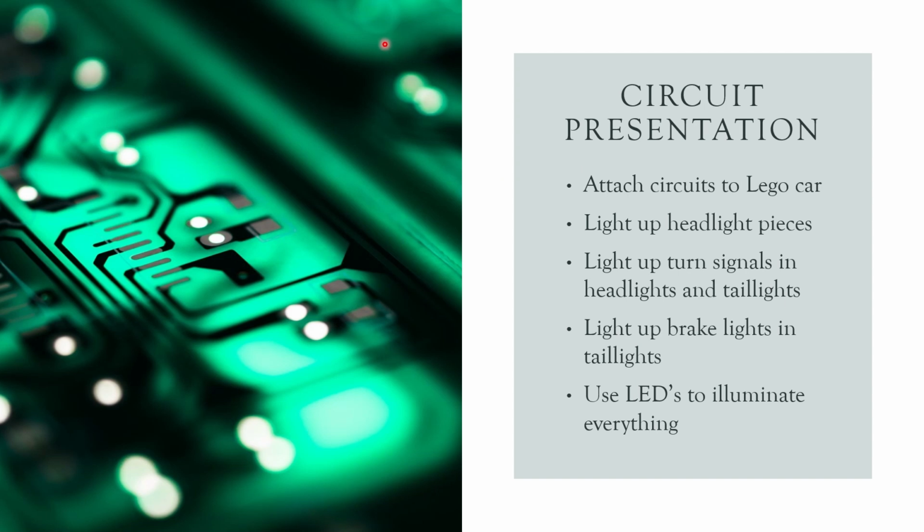To do this, we will wire all three of the circuits, solder them into a perf board, then attach it to the bottom of a Lego car. We will then drill through some of the Lego pieces and wire buttons or switches into the driver's area of the car to make the controls accessible to the little driver. We will make sure that everything is attached that way.